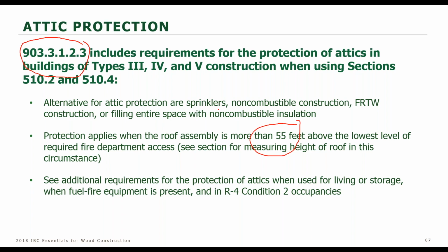Basically what this comes down to in an attic of any size is whether you have to sprinkler the attic or not. Those provisions are new. They wanted to limit in height in pedestal and podium buildings. It seemed appropriate. And there have been some significant fires. It seems appropriate to limit when you can have an unsprinklered attic in one of these podium buildings. So these are new. Take a look at those.